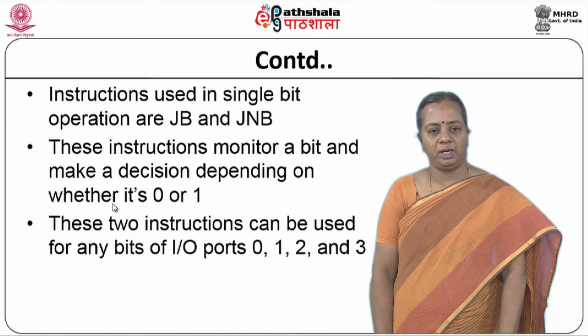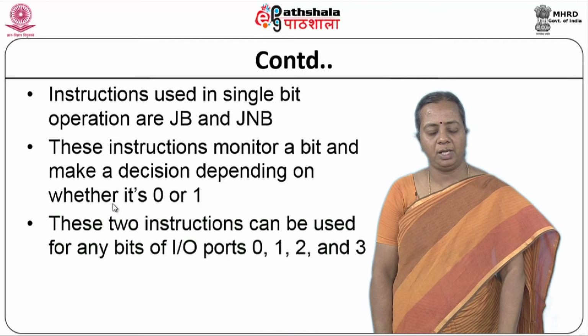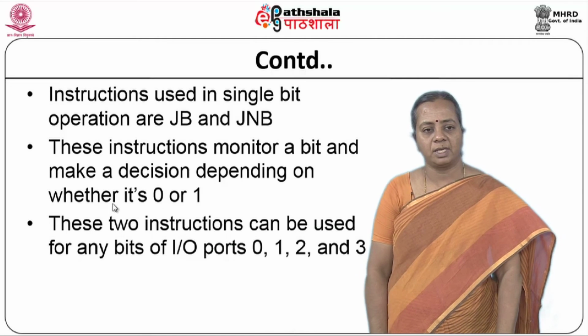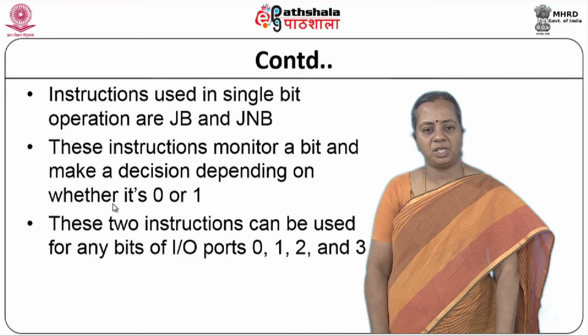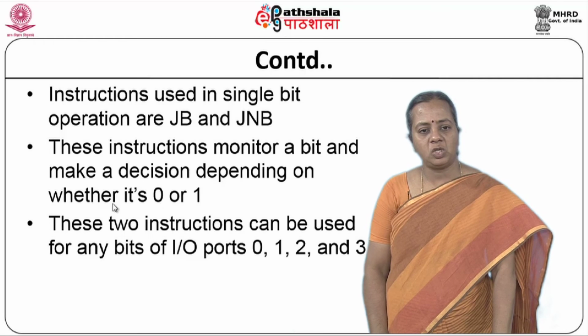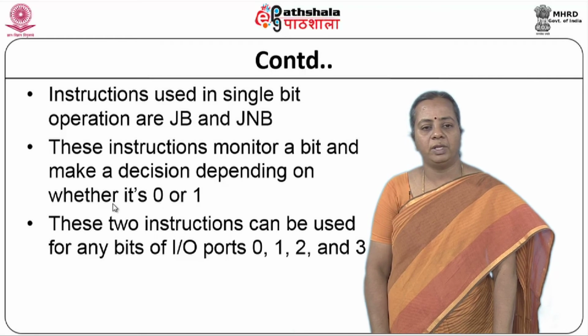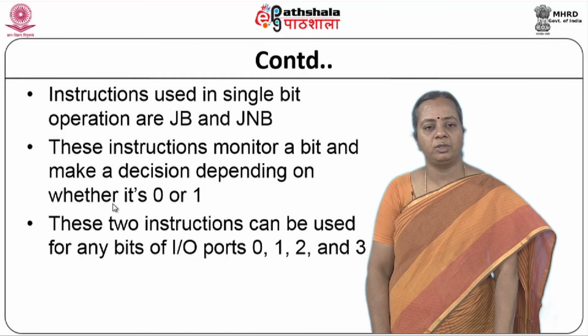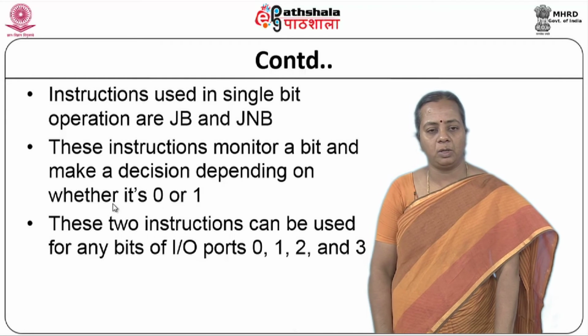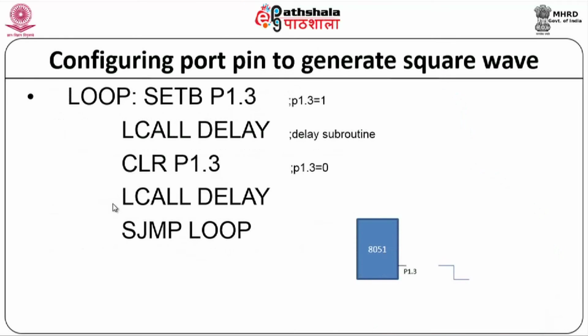Now, we have gone through single bit operations as well as how we will be accessing the ports. These instructions are used to monitor a single bit, and based on that we can decide what process to follow if it is equal to 0 or if it is equal to 1. With these ports and pins we can develop applications through this 8051 microcontroller.